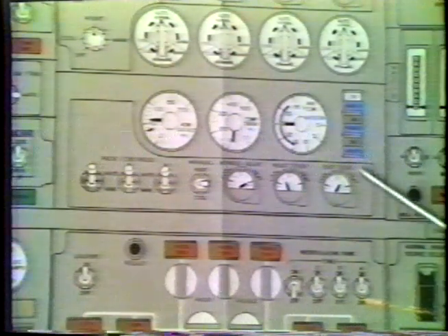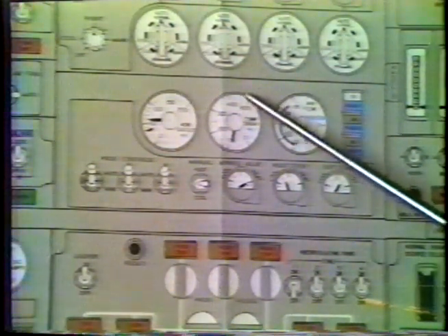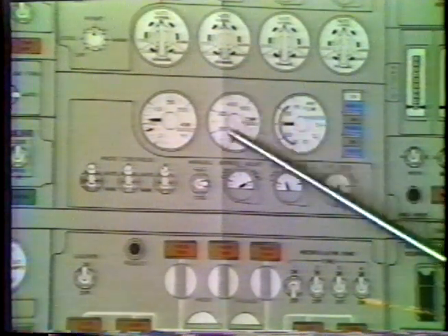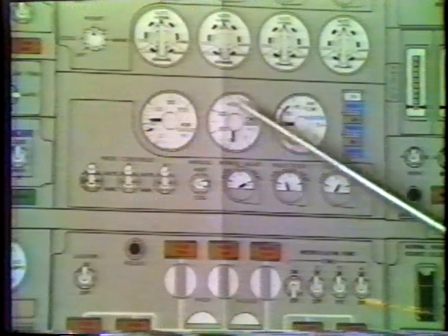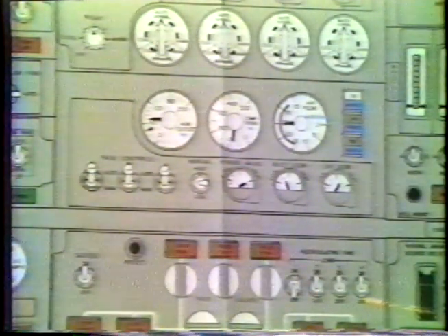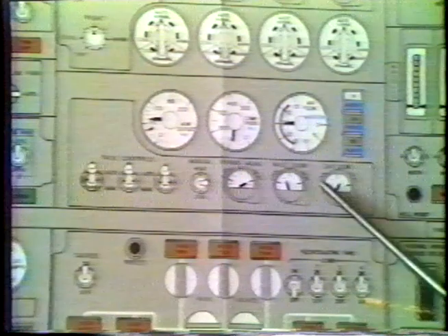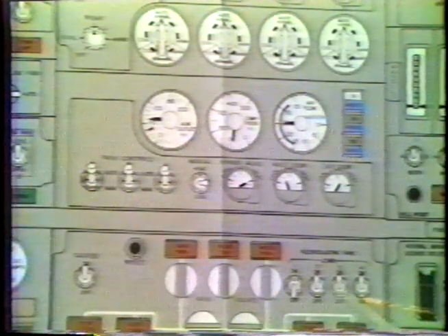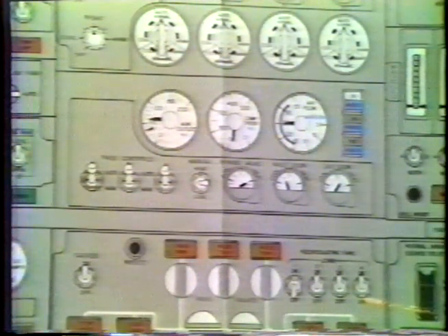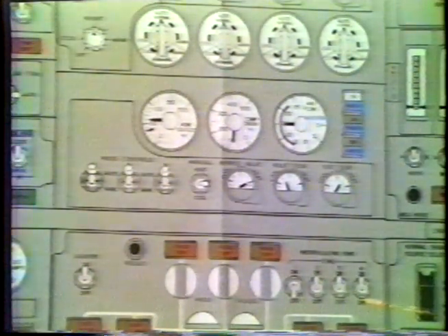The second thing that will cause a pack trip would be high compressor discharge. That also trips off roughly about the 12 o'clock position, 425 degrees Fahrenheit, and that would most likely indicate a problem with an inlet or exit door, or the heat exchanger is plugged up.